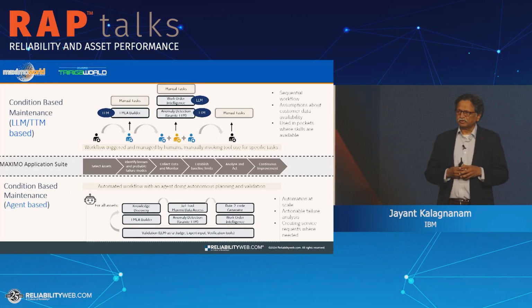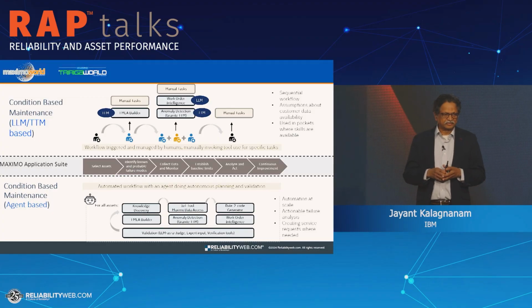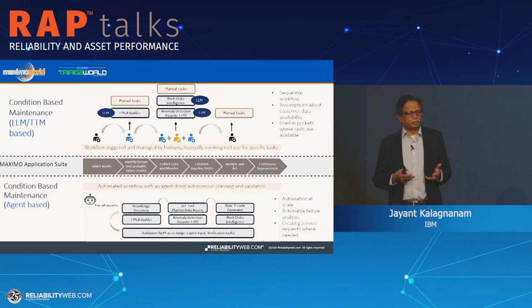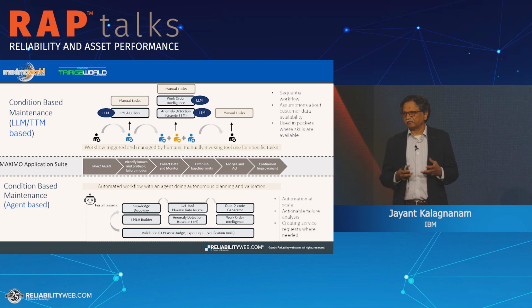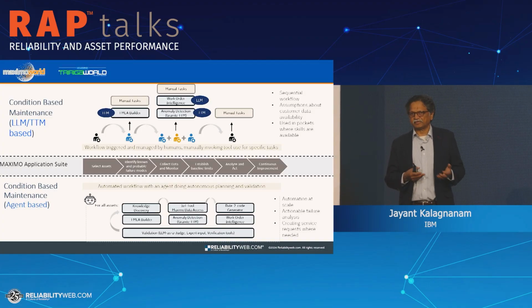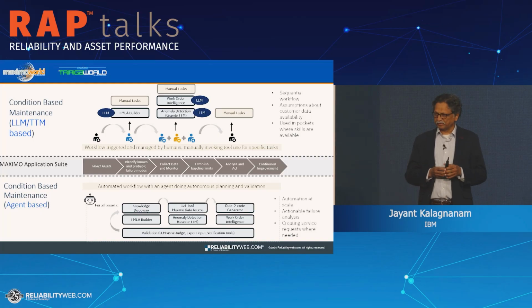So now comes the question of, if we want to do these kind of condition-based workflows as part of our asset management strategies, how do I help to automate these workflows? So you might ask the question, why automate? First of all, condition-based management has some complex tasks that are involved. First is, for example, understanding the FMEAs or the failure modes of an asset, which requires fairly deep domain expertise. And then on top of it, you need some data science to be done to understand how do I use sensor data to evaluate or estimate for specific conditions that are specified by the FMEA.